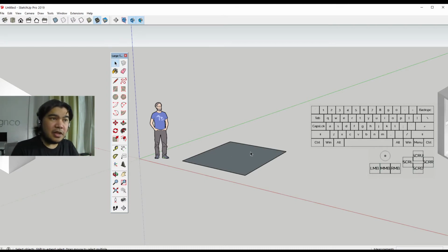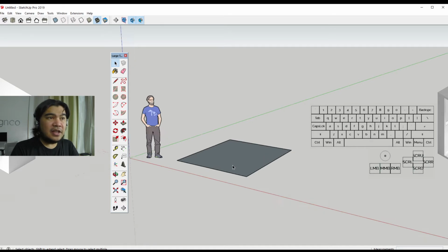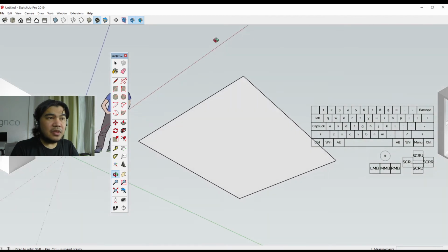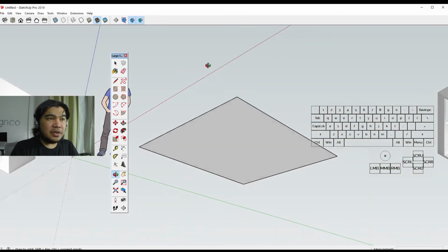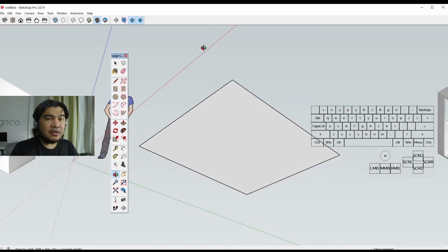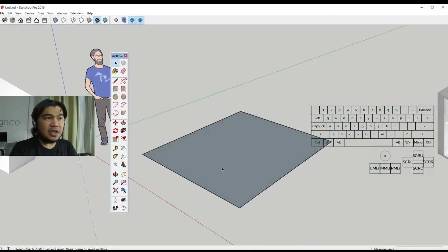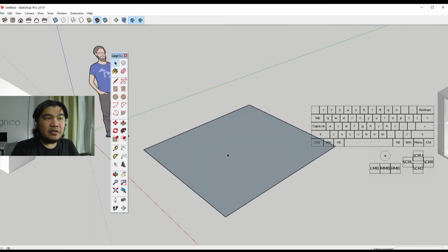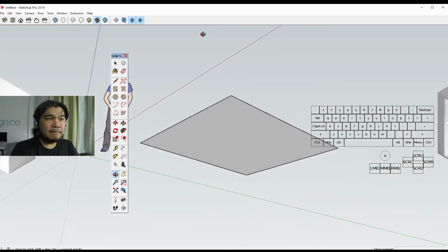Now, as you can see, when we close off a polygon, it immediately creates a region. This is what it's called in CAD. Here it's a face, and it's basically a face that is reversed. So in SketchUp, there's also that concept: there is a face that's facing you and the reverse face, and you might be wondering why the reverse face is facing us when we just completed that polygon.